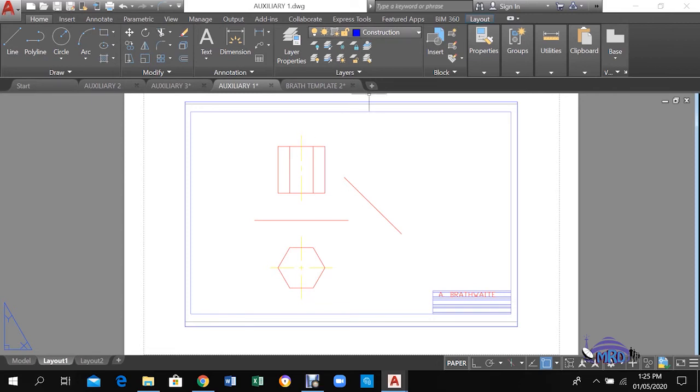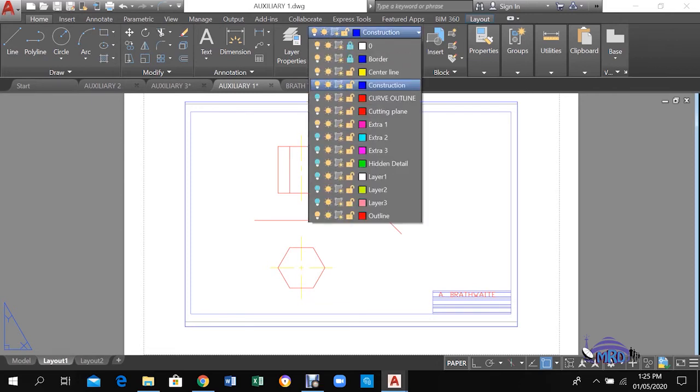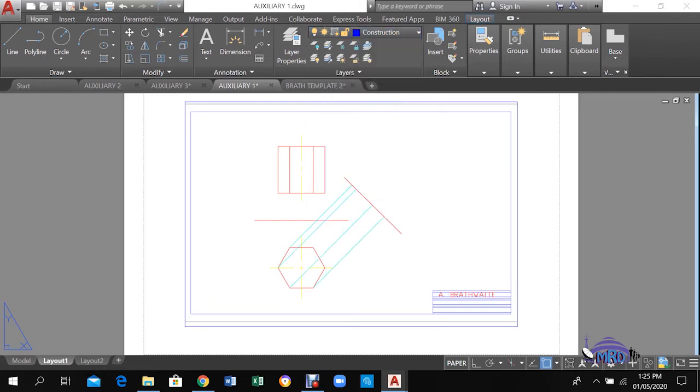And the first thing that will happen with regards to this construction then is that we will start to project lines for those angles. So 45 degrees, the 4 corners that you can see, those lines go up to your XY line. And once we have those in place, then this is the XY line here. The heights are what we will be required to mark off from that XY line.